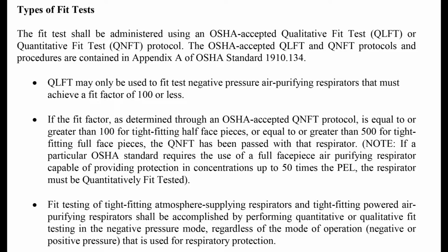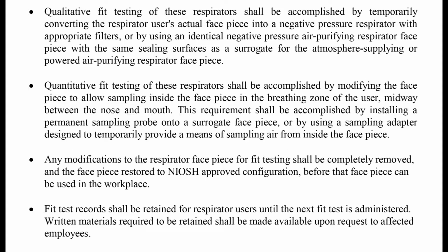Fit testing of tight-fitting atmosphere supplying respirators and tight-fitting powered air purifying respirators shall be accomplished by performing quantitative or qualitative fit testing in a negative pressure mode, regardless of the mode of operation, negative or positive pressure, that is used for respiratory protection. Qualitative fit testing of these respirators shall be accomplished by temporarily converting the respirator user's actual facepiece into a negative pressure respirator with appropriate filters, or by using an identical negative pressure air purifying respirator facepiece with the same sealing surfaces as a surrogate for the atmosphere supplying or powered air purifying respirator facepiece.